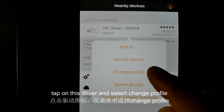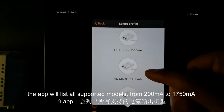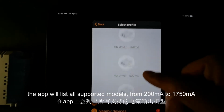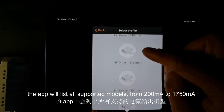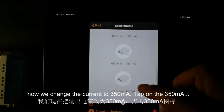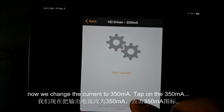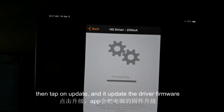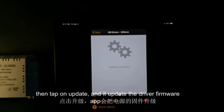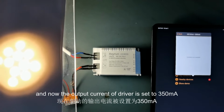We tap on this driver and select change profile, and the app will list all the supported models of the driver, from 200 mA to 1750. Now we change to 350 mA, tap on the 350, and select update. The update will update the firmware of the driver, and now the driver output current is set to